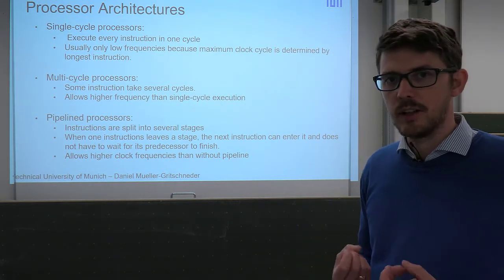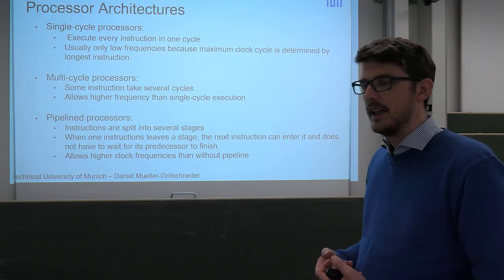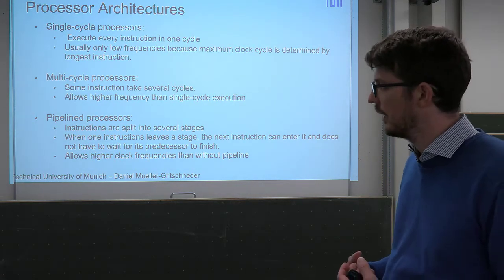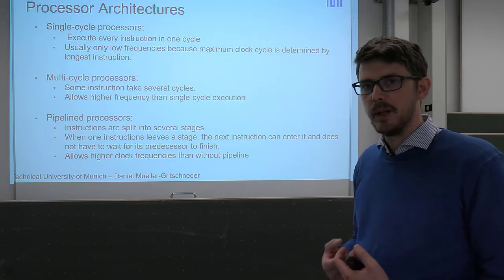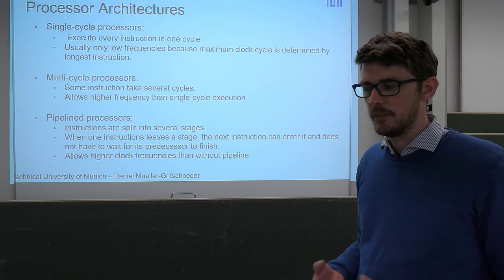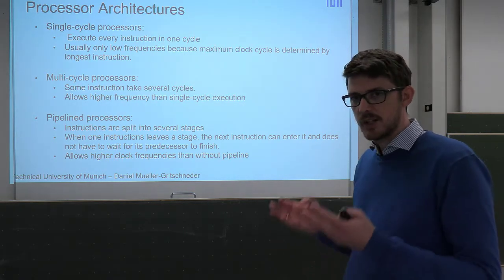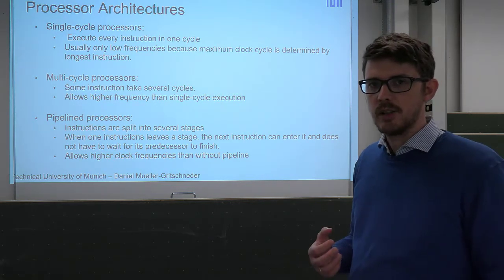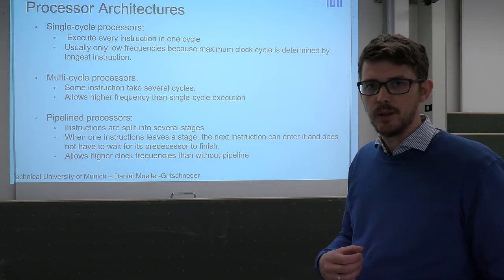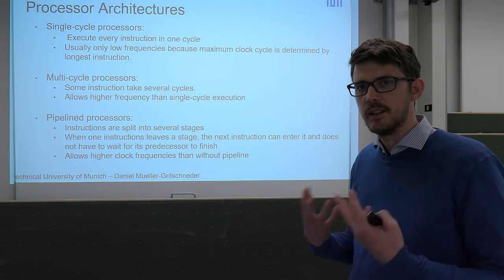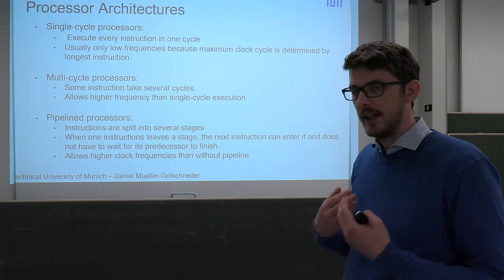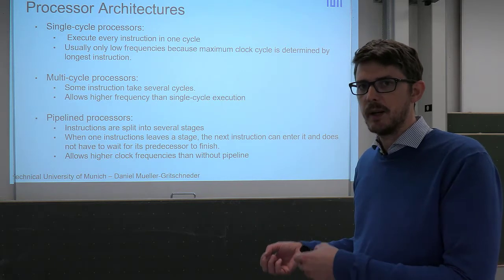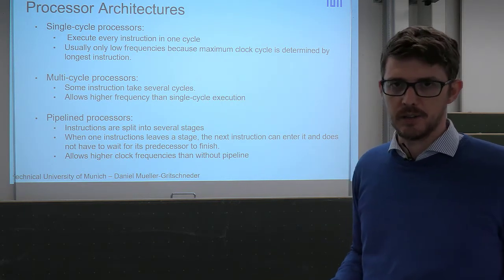And then, and this is usually the standard design, there's a better way of doing it, and this is usually what always happens if you're going for hardware: you try to build a pipeline. So you're trying to pipeline your hardware. That means you split the instruction into several stages, and when one instruction leaves a certain stage, the next one can go into the stage. So you have this interleaved execution of instructions, and make very good use of each stage, because while one stage is occupied by one instruction, the other stages are occupied by other instructions.